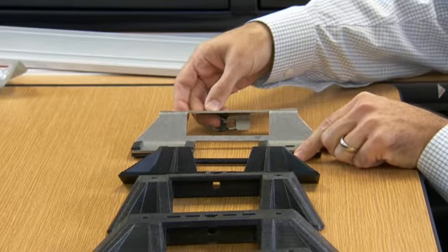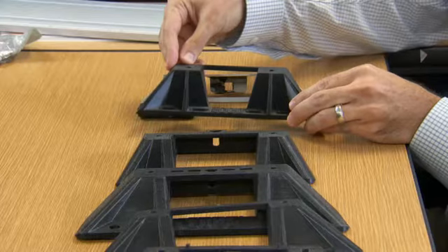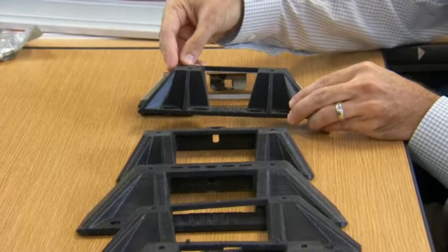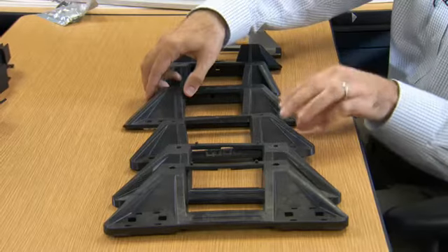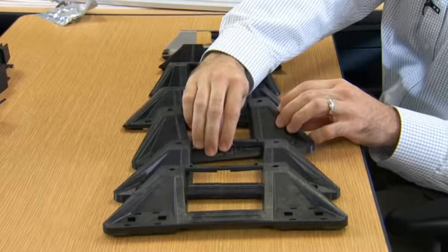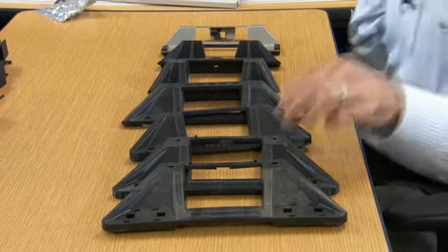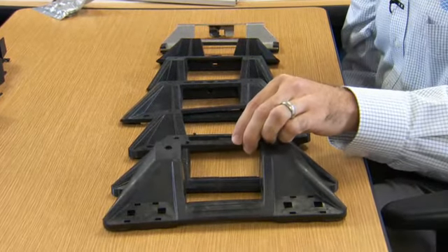So what we did is we started with a basic design, was able to print it using SOLIDWORKS, make a model and print it on our FDM printer, and then from there tweak the design if it means adding fins to make it more structurally sound, adding other features for more aesthetics. And so we went through a number of iterations, adding some aesthetic things, moving ribs around to get that final part until we had an actual tooled part made of glass-filled nylon.